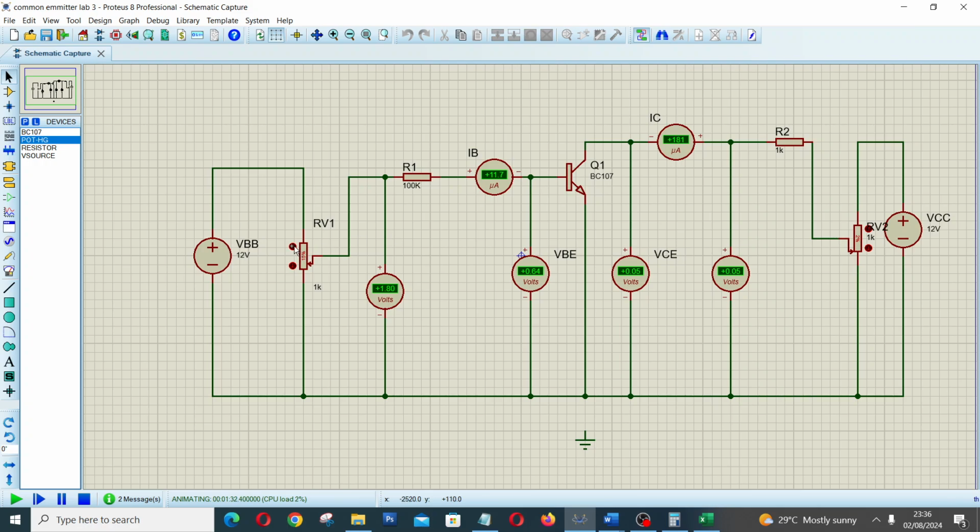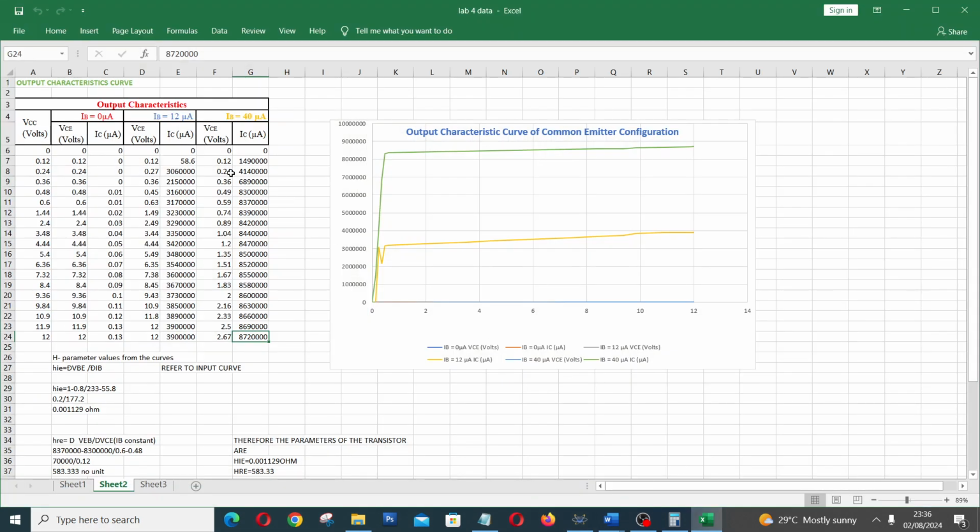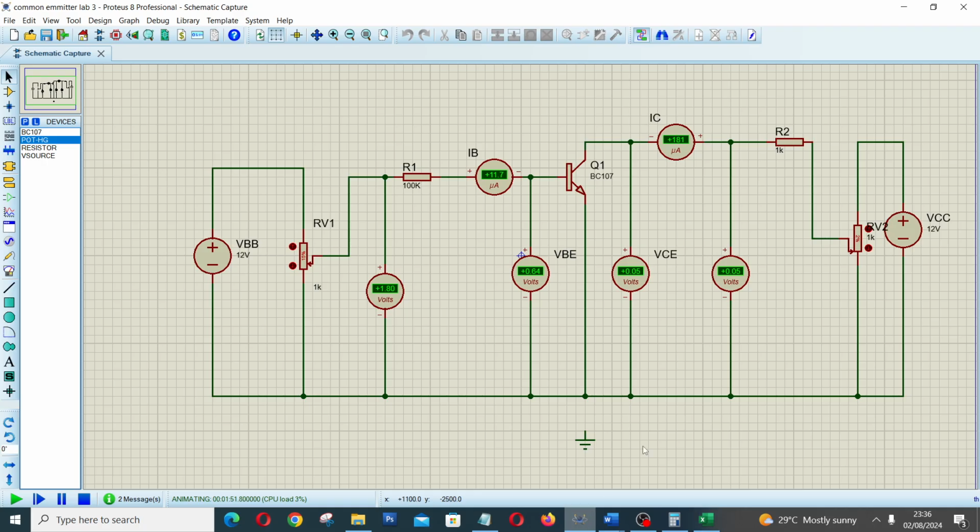So you try to set this thing close back to 12 microamps. So 11.7 is the closest to 12. 11.7 is just 3 points from 12. Okay, so we can leave it like this and take a measurement. So this is how we are going to get the values for IB equal to 12 microamps. And when you are done with that, you go to the experiment again.